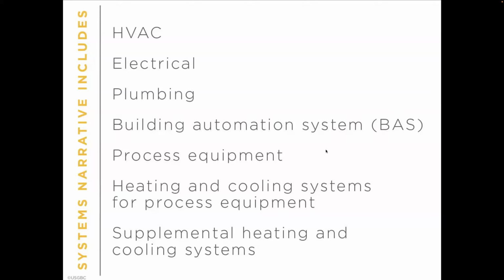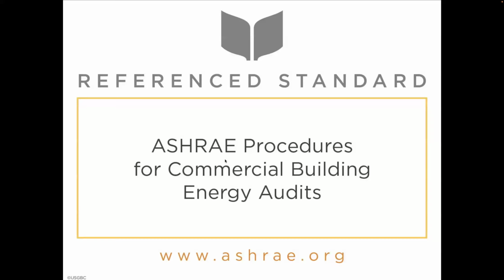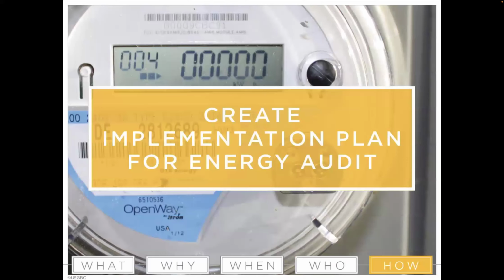All right. A lot of these procedures are based off ASHRAE. A lot of the energy standards on audits and energy performance are based off ASHRAE standards. For energy, it's 91.1, I believe. That's something that you probably want to be aware of. For indoor air quality, it's ASHRAE 62.1, I think. And then for thermal requirements, it's ASHRAE 55. If you're a LEED GA, you already kind of knew this, because those are the things you had to know then. So ASHRAE standards set these set points.